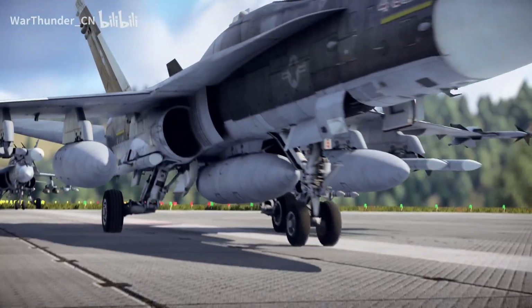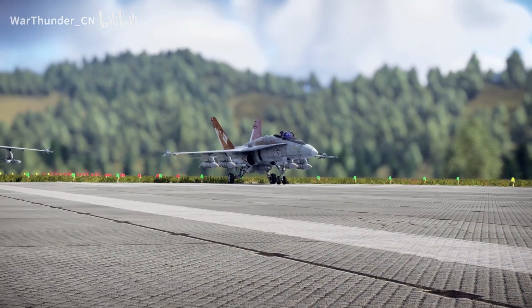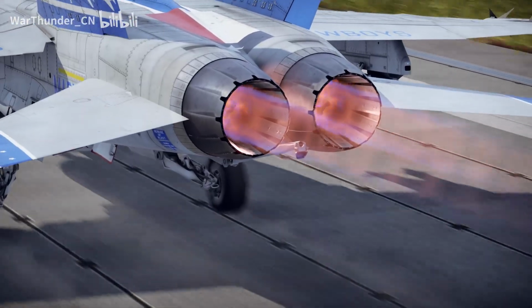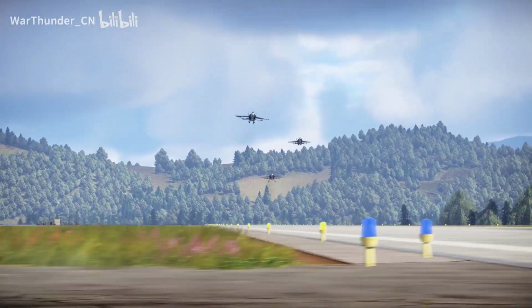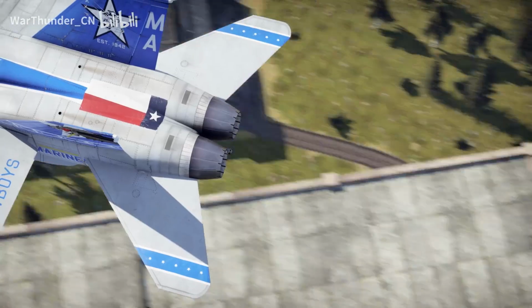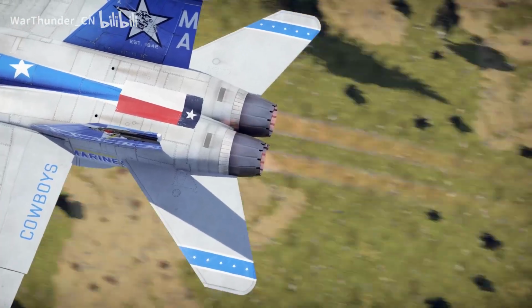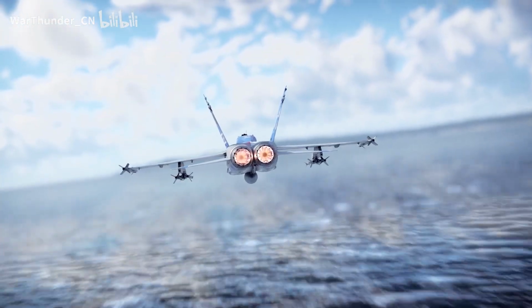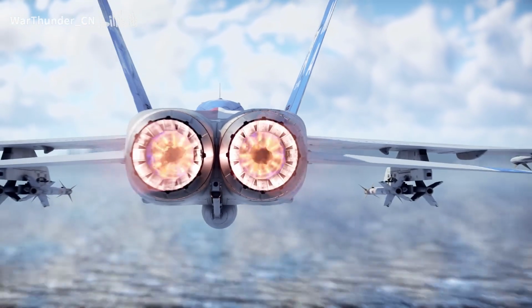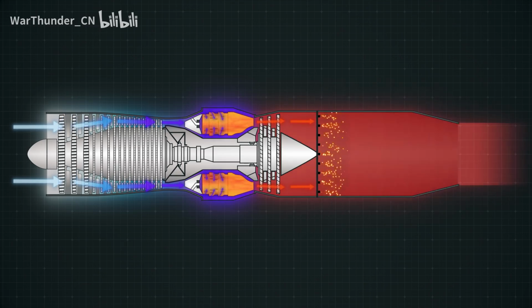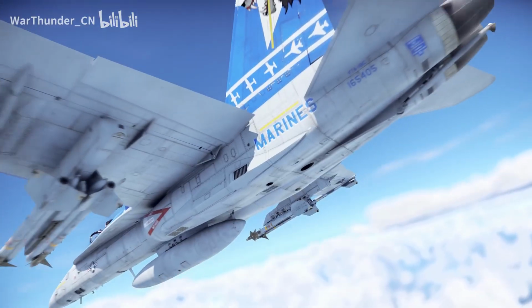To boost thrust for military aircraft, engineers took a different approach. That solution was the afterburner, a combustion section placed between the turbine and the nozzle. Additional fuel is sprayed and ignited there, dramatically increasing temperature and thus exhaust velocity. Why is secondary combustion even possible? Because turbojet exhaust still contains some oxygen. Only part of the incoming air actually burns in the main chamber. Much of it flows around the chamber for cooling, then mixes with the exhaust. That leftover oxygen allows extra fuel to burn in the afterburner.